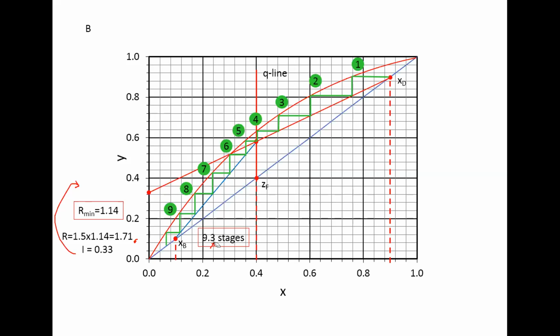Okay. Any other question? Miss, we can know the ratio of liquid and vapor based on the feed condition, right? Yeah, correct. It will be given. Usually it will be given. But if you are not given that information, you might be given the actual reflux, and from the actual reflux, you can find where the feed enters your column.